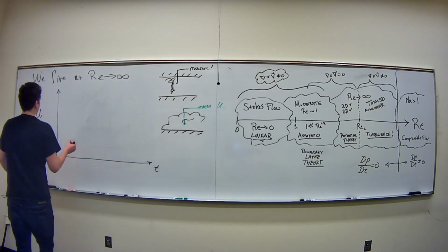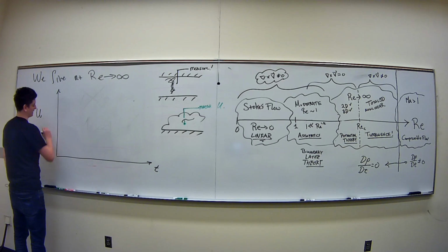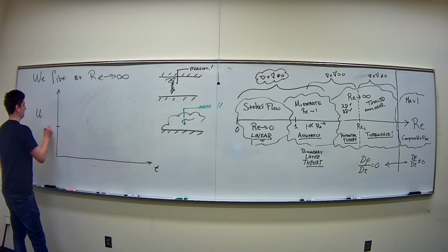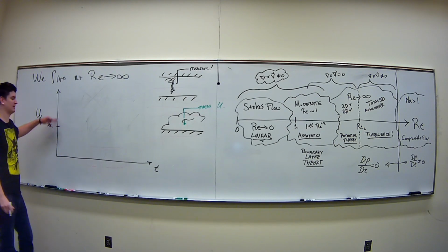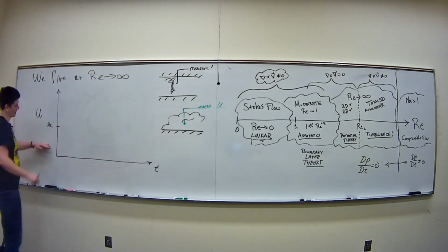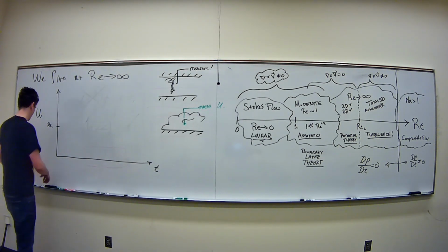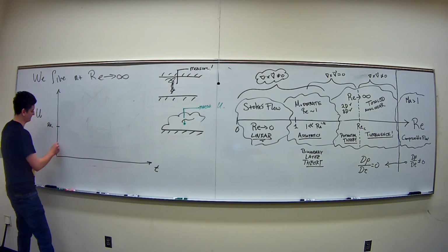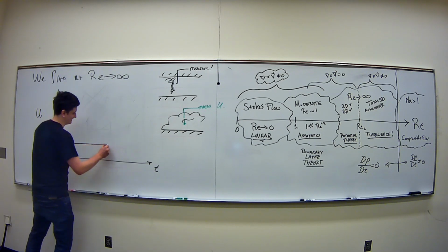Either way, you get the classic graph. You've seen this maybe multiple times, but let's put it right here. If I'm at some really slow regime, maybe around here, there's some litmus, certainly something going on where after I go up and up and up and make these measurements, something changes qualitatively. So what's changing? Well, if I'm below there, you're in your laminar flow case, at steady state conditions.